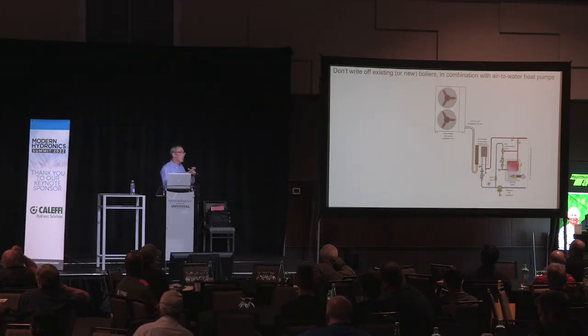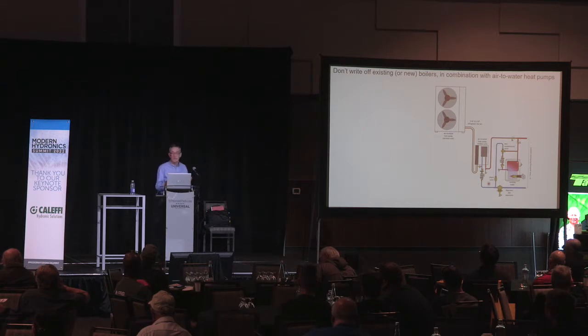So if you're going to add insulation to a building, do a deep energy retrofit, you're bringing the load down substantially. You're also bringing down the water temperature that you need to operate that system at. Basically, water temperature comes down in proportion to load reduction. Quick numbers that I happen to remember: imagine an original building with a 100,000 BTU per hour design load. Let's say you add insulation, improve the windows, air seal it, whatever you do, you bring the load down to 70,000.